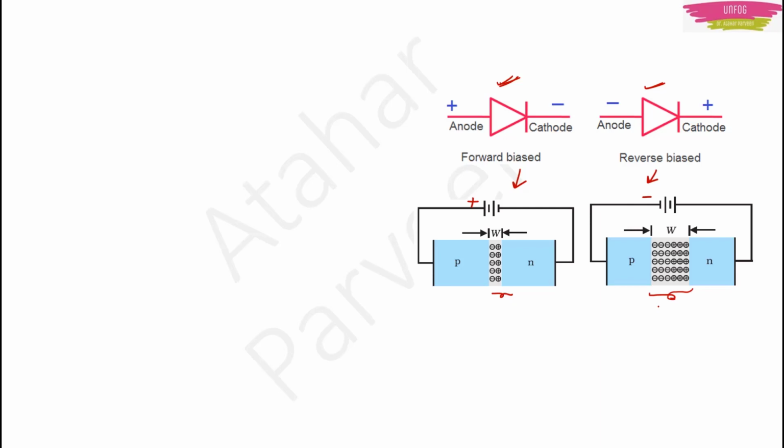First let us talk about forward bias. In forward bias, holes from P type are moving to N type, right? And electrons from N type are moving to P type region, right? Now what is happening here? The depletion layer is very thin in forward bias. This is happening because more and more current is flowing. More current will be flowing in the PN junction diode, so it will force the depletion layer to decrease, because fewer electrons and holes will get trapped here because there is more current.